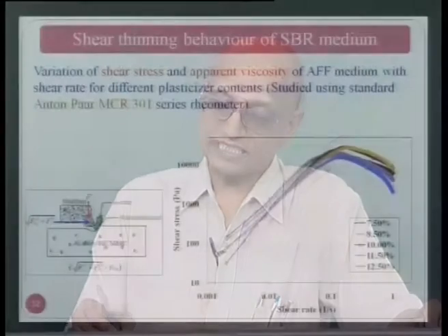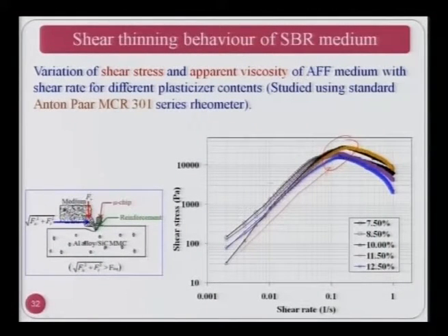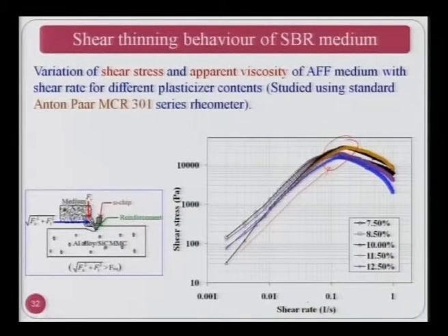But when shear rate increases up to a certain value shown over here, then the shear stress or shear capability of the medium starts decreasing, and this phenomenon is known as shear thinning. This is really able to explain many of the results which have not been explained so far, as far as the abrasive flow finishing or rotary abrasive flow finishing process is concerned, and from that point of view, this curve is very interesting.